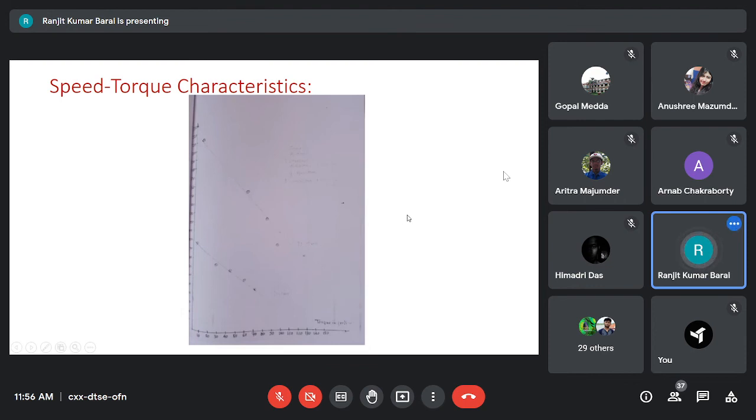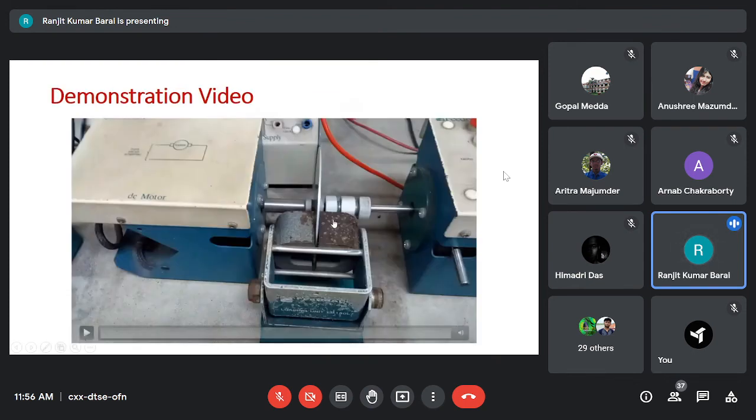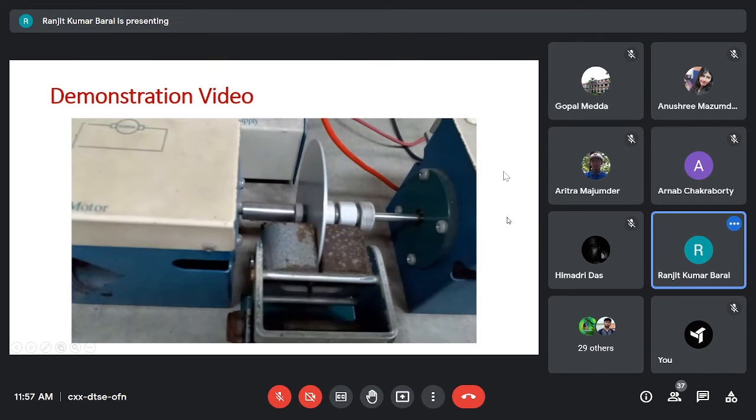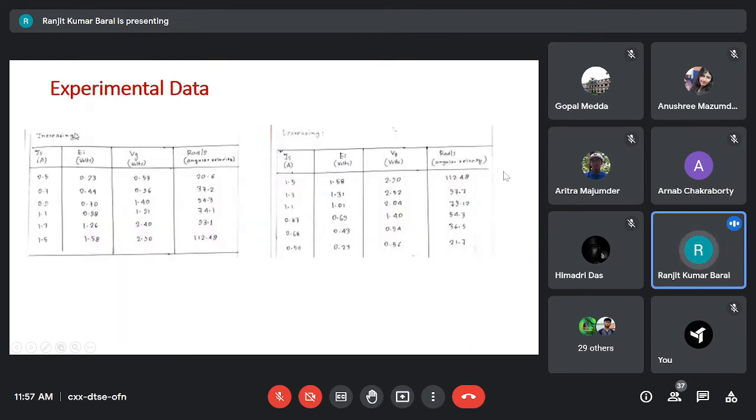The next run is to find out the non-linearity, if any, present in the system. For that, we take a fixed brake position and we continuously increase the input voltage and keep a look on the armature current reading. We will allow the armature current to go up gradually. We cannot perform the experiment in the reverse direction. Once we have started, we will just go on increasing.